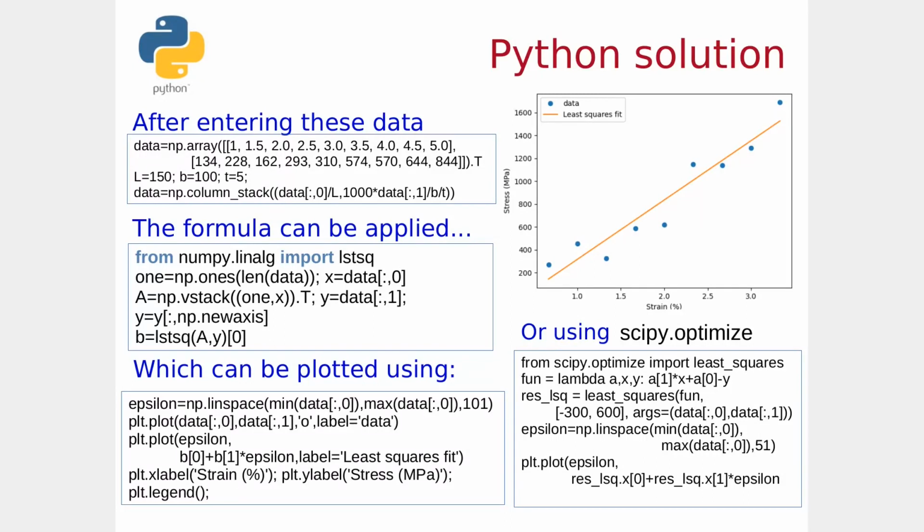force into megapascals. That is to say, I've divided the force in newtons by the area, the breadth multiplied by the thickness, or divided by the breadth then divided by the thickness, however you want to look at it, to provide the area, so that's force over area, and the value is in newtons per millimetre squared, which is the same as the megapascal.